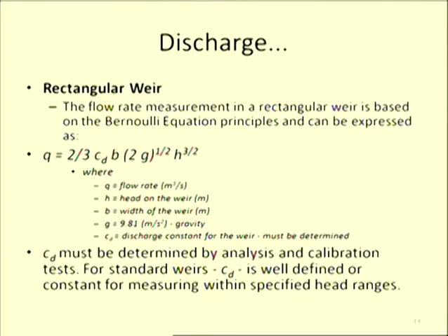This is a particular equation for measuring flow of the rectangular weir. You need not worry. This is for making you understand how flows are measured. You just look at this equation: what we have seen earlier, that H is there with index 3/2. What we have seen, that was n. This 2g is also a constant.